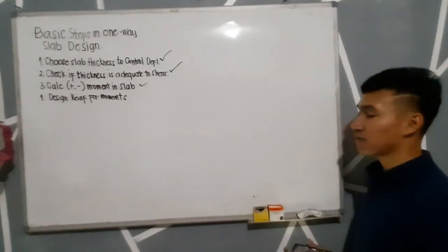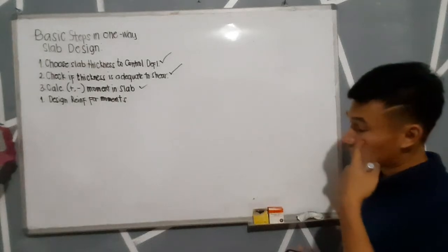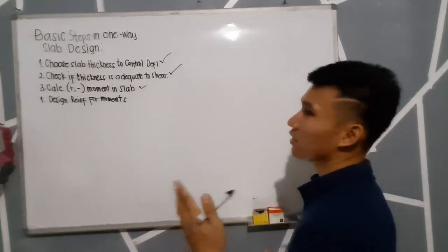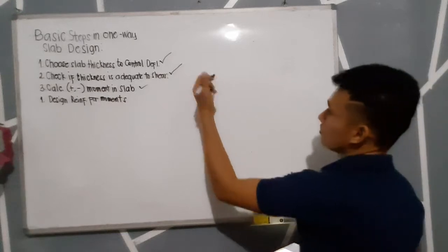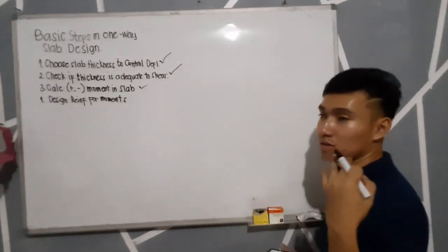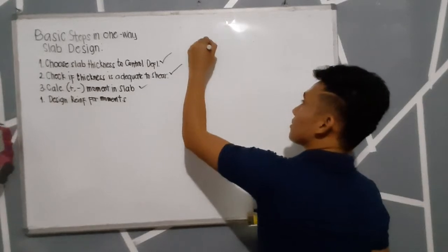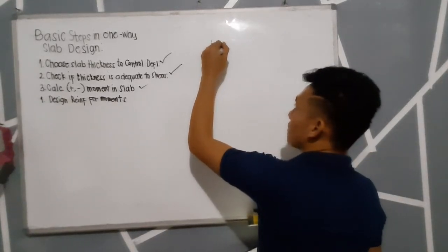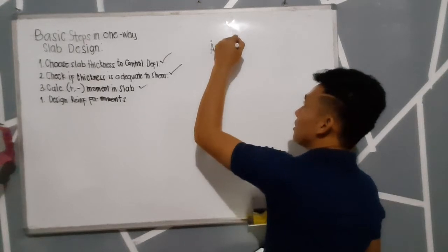So after comparing the steel ratio to the maximum steel ratio, we now proceed to comparing for the minimum. The minimum here is the minimum area of steel, and the calculated rho value we got earlier is used for the area of steel. So in comparing the area of steel to the minimum area of steel, first, the area of steel is just rho times the area gross, or the bd.